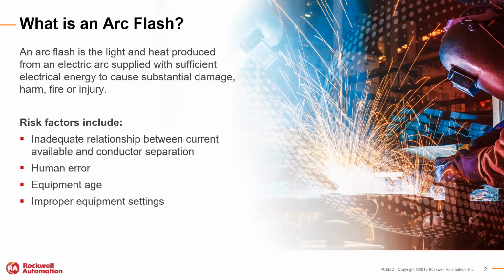To start, I'm sure many of you on the phone are familiar with what an ArcFlash is, but I'll just highlight it pretty quickly here. An ArcFlash occurs during an electrical fault or short circuit condition, which passes through an arc gap. An arc flash can be initiated many ways. It could be through accidental contact with an energized electrical circuit. You could have equipment at a facility that's technically underrated to handle the available short circuit current in a particular circuit. That causes an electrically unsafe condition.